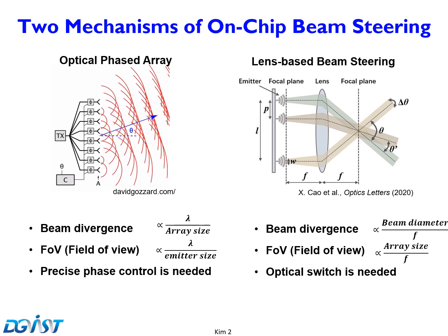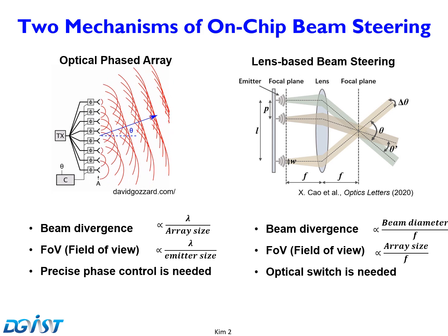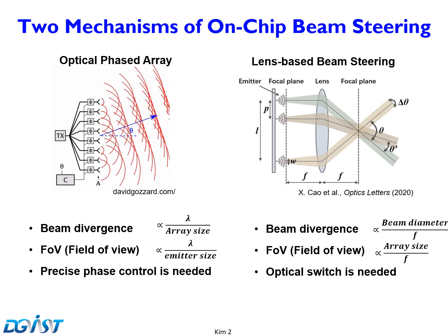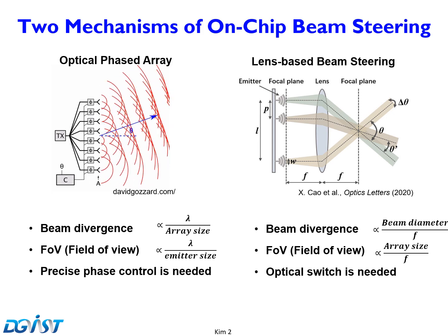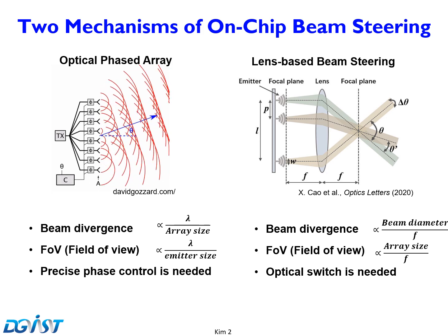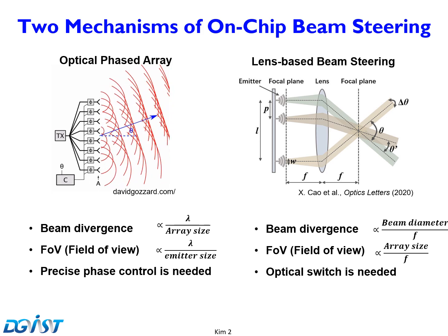The optical phased array is widely researched, but it needs precise control of the whole array and has an initialization problem. A trade-off between the array size and the beam divergence is also a problem. We can solve these things by using a lens-based approach.